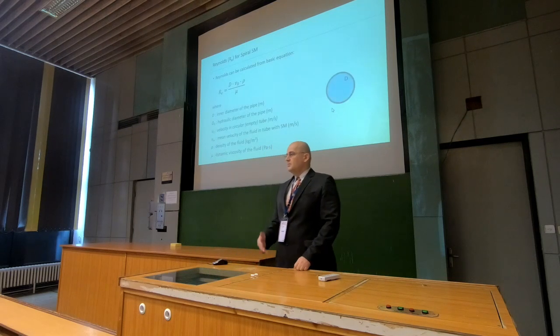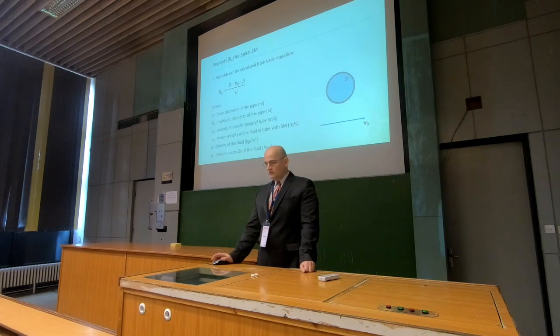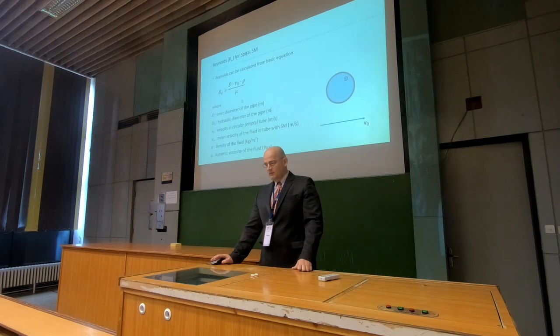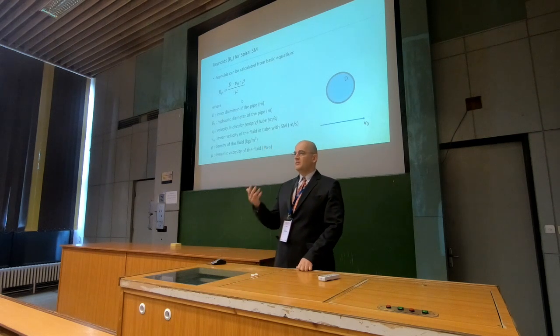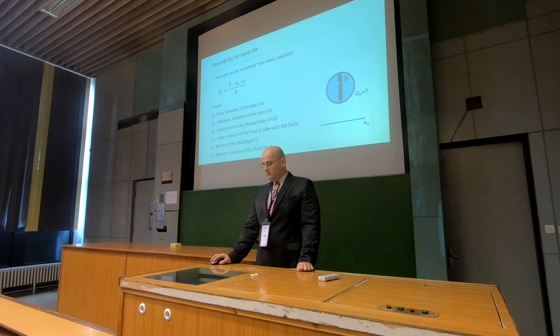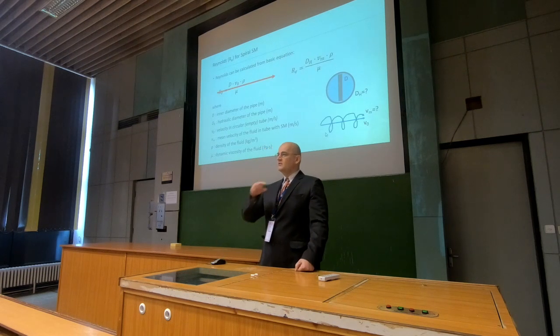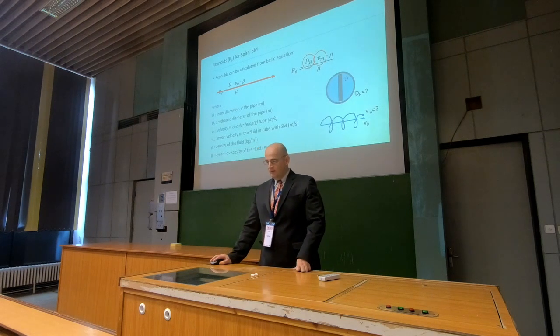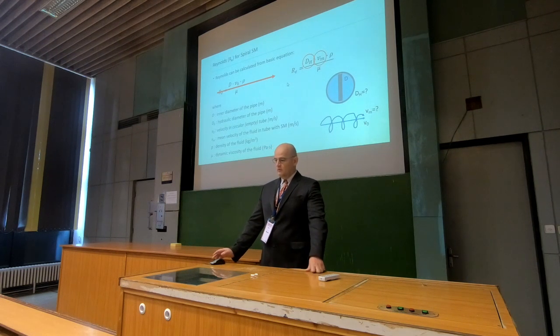The Reynolds number can be easily calculated with the existing equation, where we take the inner diameter of the pipe multiplied by velocity multiplied by density and divided by the dynamic viscosity, but it is for an empty tube. Since we have a static mixer installed here and the path is not linear but spiral, we have to modify these two numbers. We have to calculate the hydraulic diameter of the pipe and the mean velocity of the fluid in the tube with the static mixer.